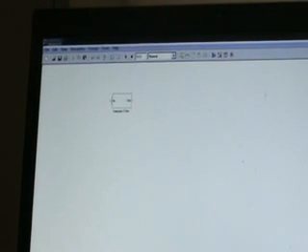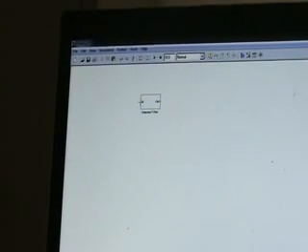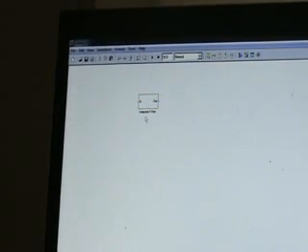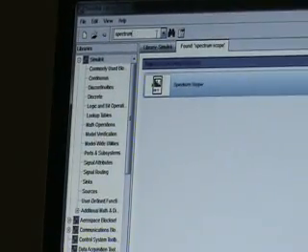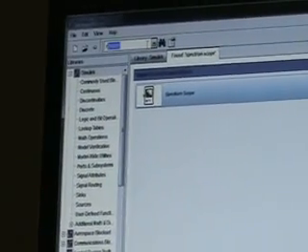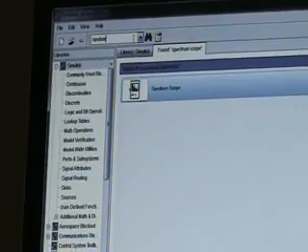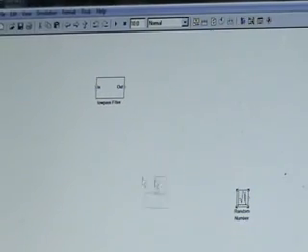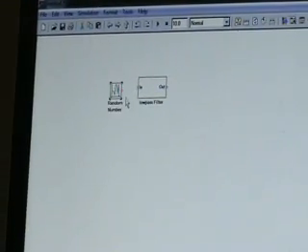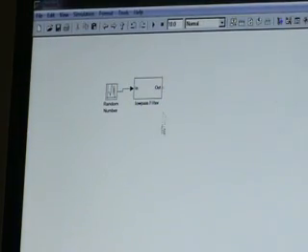For this we need to give an input to the low pass filter. We give a random input to the low pass filter. This input can be taken from the Simulink library browser. Here we give a random input, so click random. This we add to the untitled model. We get the random number generator. We give this as input to the filter.